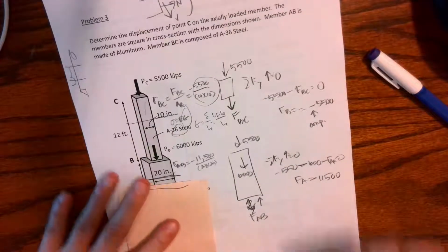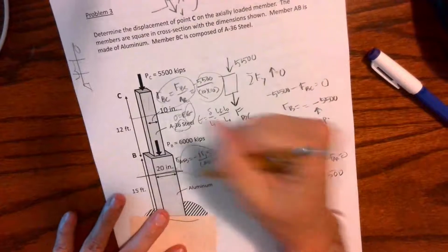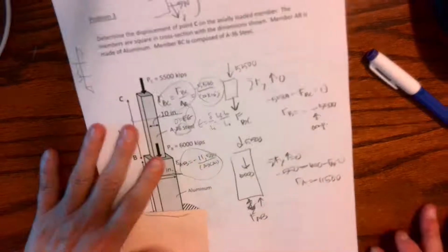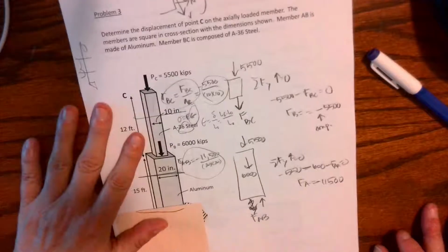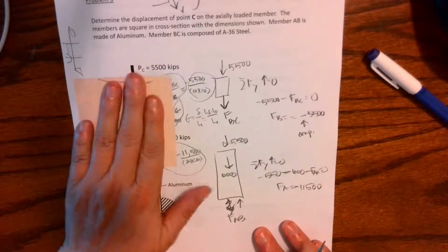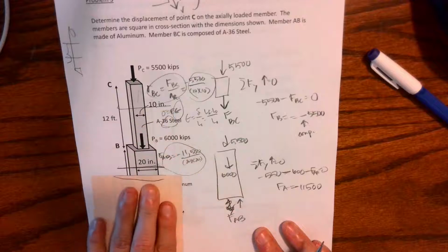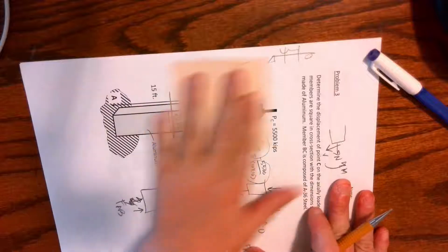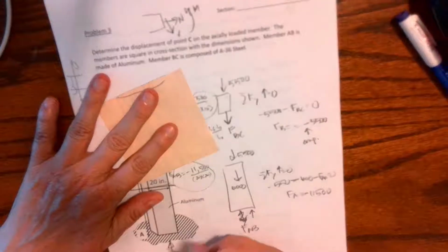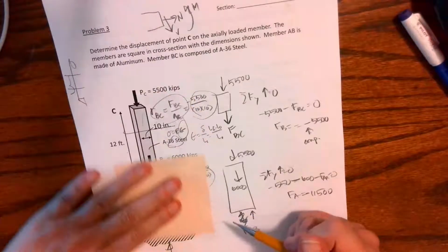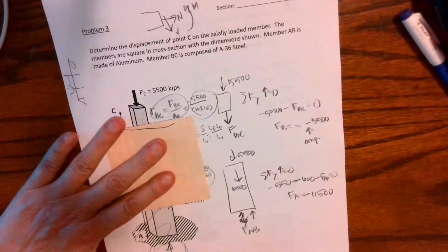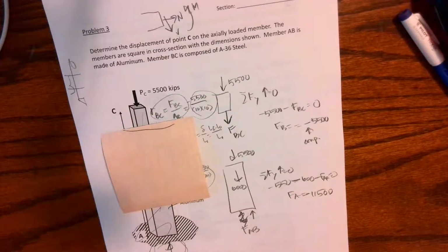It's just taking the same equation. I have to use the same equation, whether it's stress or strain or whatever, for every single section. And I have to include everything that's above my line, or if it's going sideways, everything to the right. If I want to start with the support, I would have to come down here and find my reactions, because I would have to include the reactions as I went up. Otherwise, as I'm going up, if you don't have reactions, there's no force there, which we know isn't true.